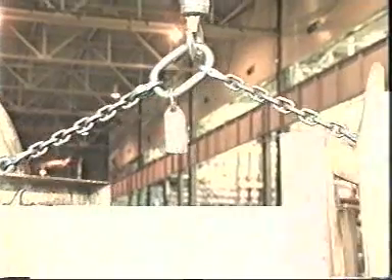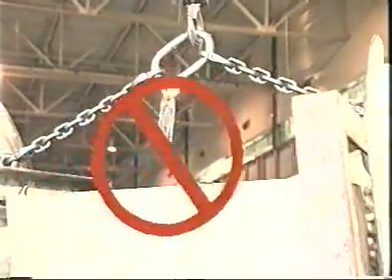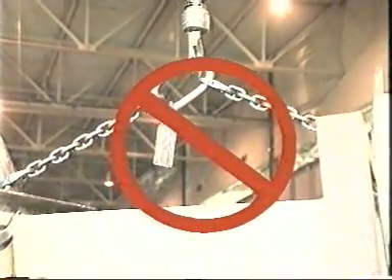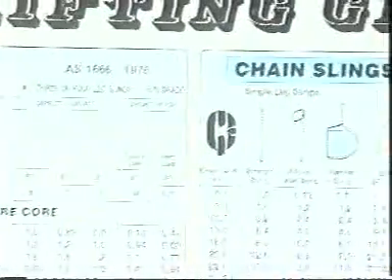If you're creating unsafe sling angles with slings that are too short, then get a longer sling. Make a point of consulting the manufacturer's instructions and tables concerning rated sling capacities.